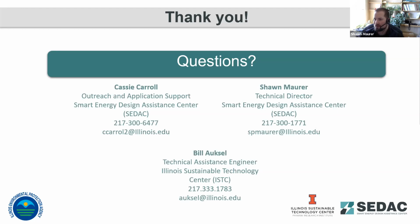If you're letting that wet well stay at a higher level, you're providing more assisting head to that pump, so there's less lift out of that station, so you can get a slightly better performance out of the pump. But as Matt was saying, you have to occasionally draw it down, to get whatever's fog, fats, oils, and grease floating on top of that cleaned out of the system.